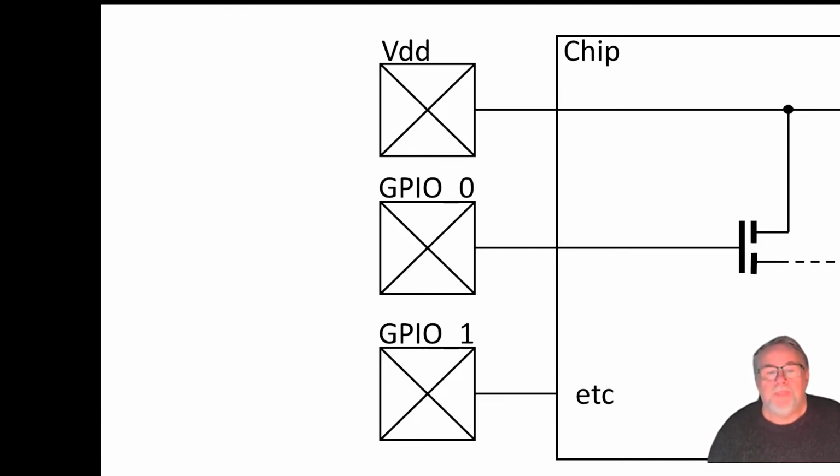First of all, if the voltage on one of the inputs, see GPIO 0 there, which goes into a MOS transistor, ever goes above the supply voltage, VDD, then the internal circuitry can turn into effectively an SCR, a thyristor that's a short across the supply lines, and basically the chip burns out. So in order to protect against that, they put in a diode there.